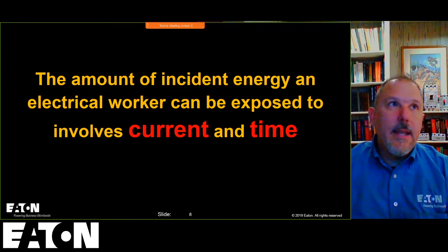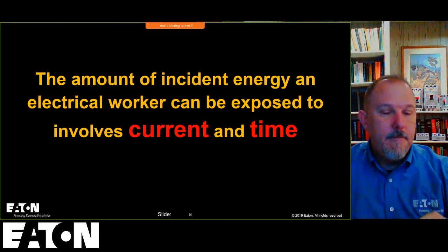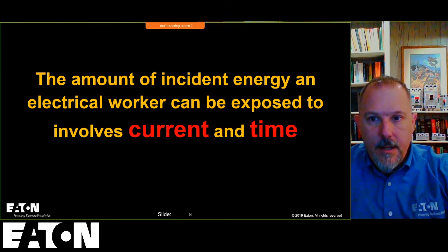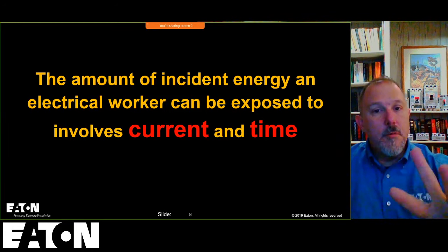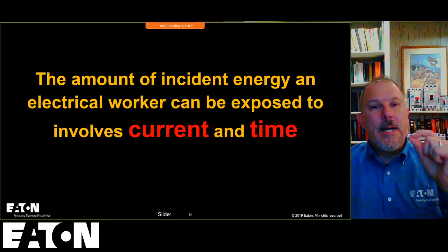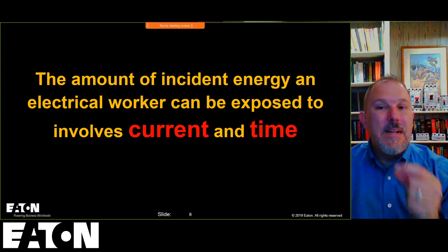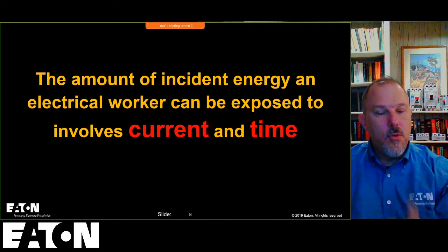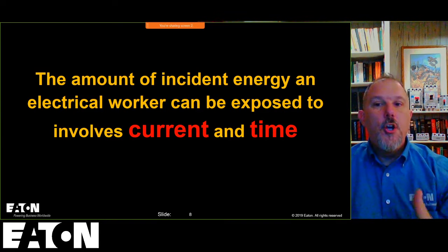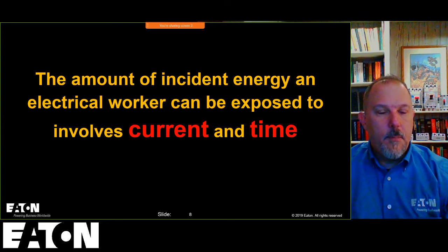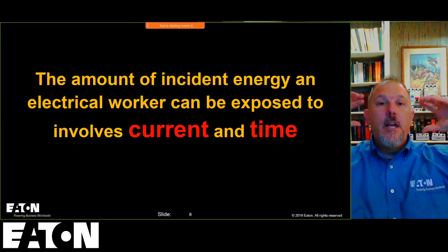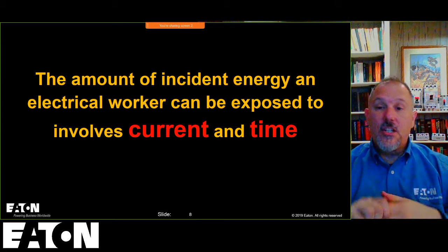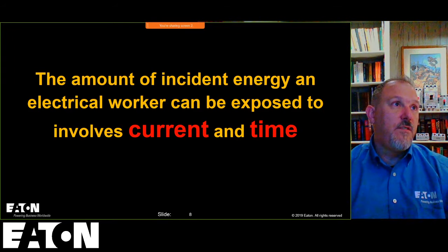All right, so I'm going to give you another video here, which is an example again of an arc flash event. I'm giving you 3 scenarios. The first one is about a 6-cycle clearing time, so 0.1 seconds. You're going to see it's a motor starter. You're going to see the mannequins being engulfed in smoke, and the pressure pressing against the mannequin. In this example, the gutter above the top of the mannequin comes off and hits the mannequin in the head. It's going to be very fast. You may or may not see that in this video.